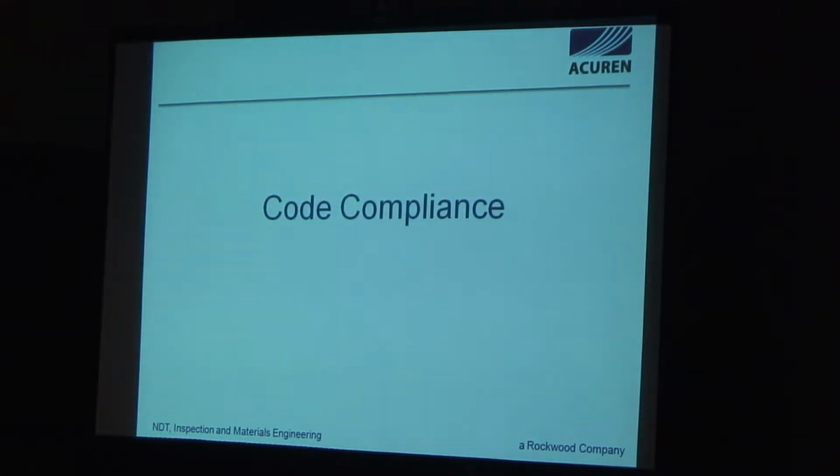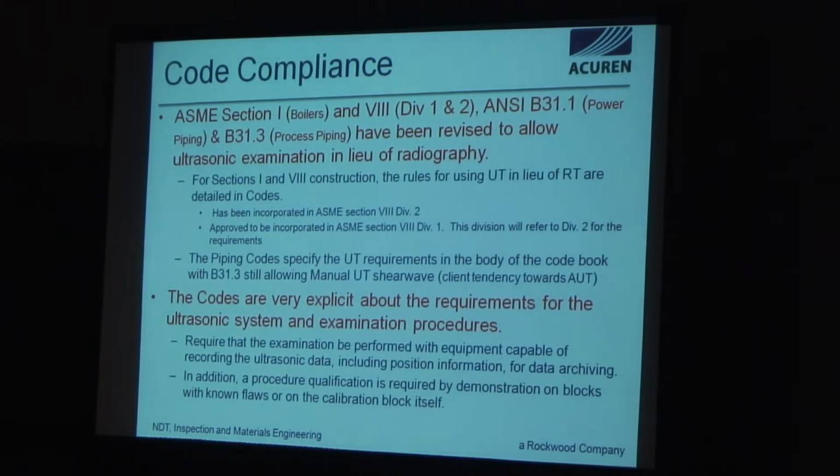Code compliance. I'm not going to talk about this too much other than the complicated nature of it. ASME, of course, Section 1 and Section 8. Been real avid users of UT and radiography. B31.1 power piping as well, B31.3. Section 5 is pretty much covered in the ASME code now. You'll see some minimization of some of the code cases, which is nice.